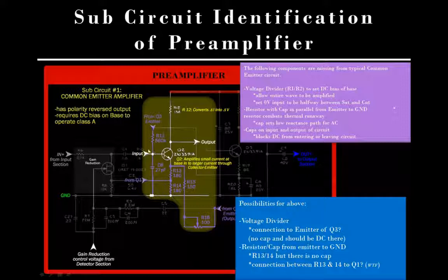If it's easy, like you say, okay, DC can't go there, DC can't go there, well, DC has to be coming here. Oh, that's a place where DC could come. If it's that quick, do it. If not, just move on and say, okay, I don't know what all these components do. And that's fine. We don't know what R11, C6, R13, R14, R15, R16 do. And that's fine. The point at this stage is not to know what everything does, it's to find the things that you know easily what they do, and then move on. And you'll start to have a real good bunch of components done.